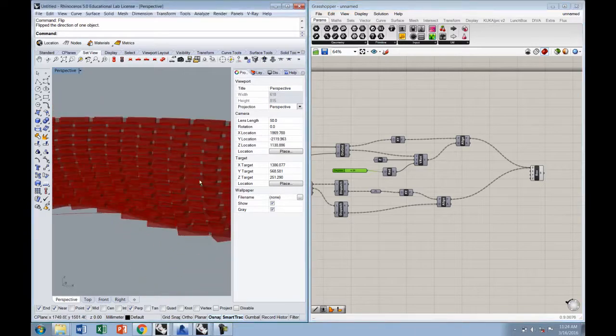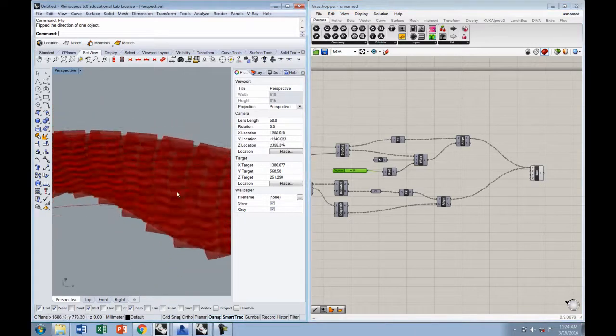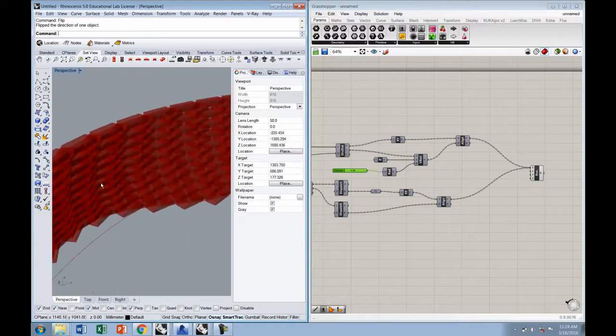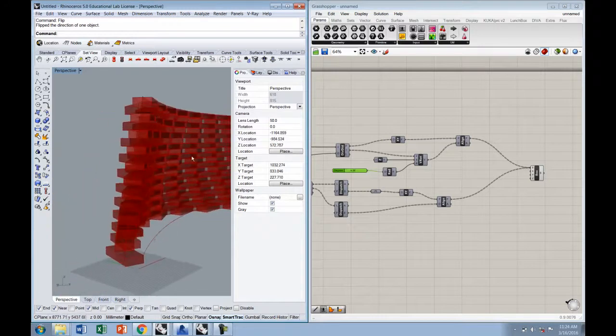And what you're going to see here is that my vectors are now kind of kicking the bricks in one of the rows, it looks like the even rows, out a little bit, and I get this much more interesting kind of texture. I want to copy paste this VROT component and do the same thing. I'm going to leave the degrees and the radian conversion and the z all the same.